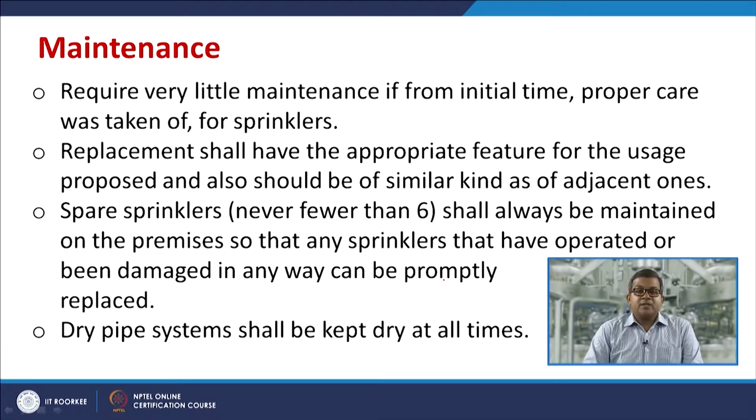Spare sprinklers, never fewer than 6, shall always be maintained on the premises, so that any sprinkler that has operated or been damaged in any way can be promptly replaced. So, this is again a standby arrangement for the sprinkler system. Dry pipe system shall be kept dry at all times. This is a mandatory requirement and it is part and parcel of your maintenance protocol.